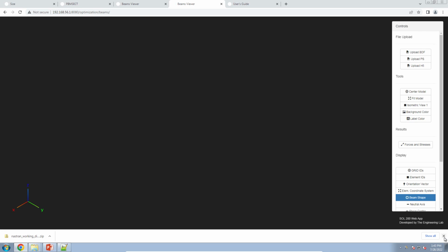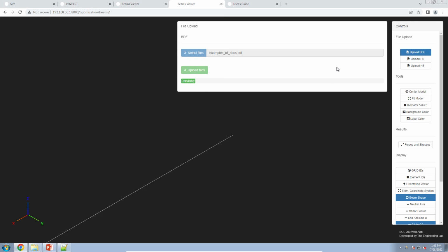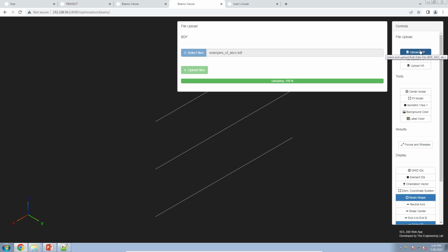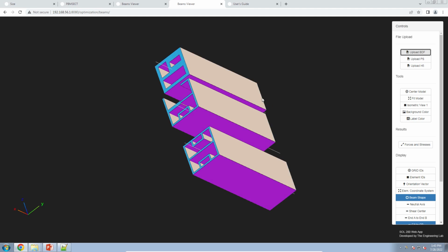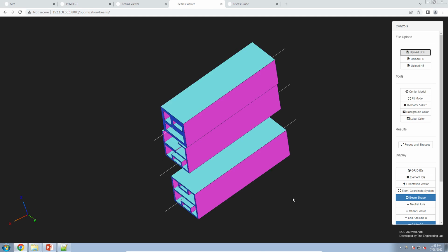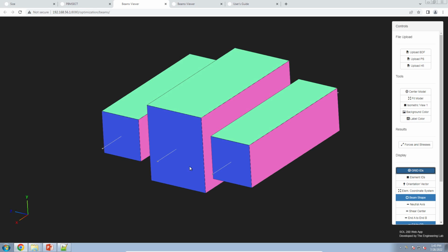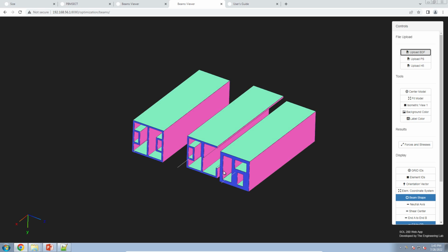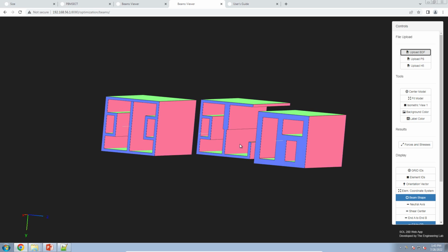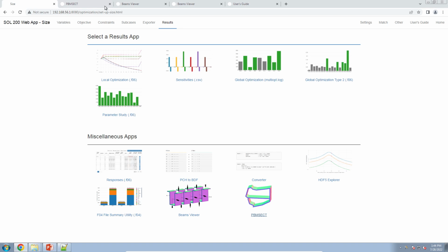And let's go ahead and import this updated bulk data file. So we'll upload this updated bulk data file. And now if things went well, we should be seeing our updated cross sections or our updated beams here that you see on the screen. So in this other window, this is what the 3 beams look like before. We were just using these PBARs and these PBEAM entries to define the beams. But now we're using the PBMSECT and the PBRSECT entries to define our arbitrary beam cross sections for these 3 beams. So I think that is basically the end of the tutorial.